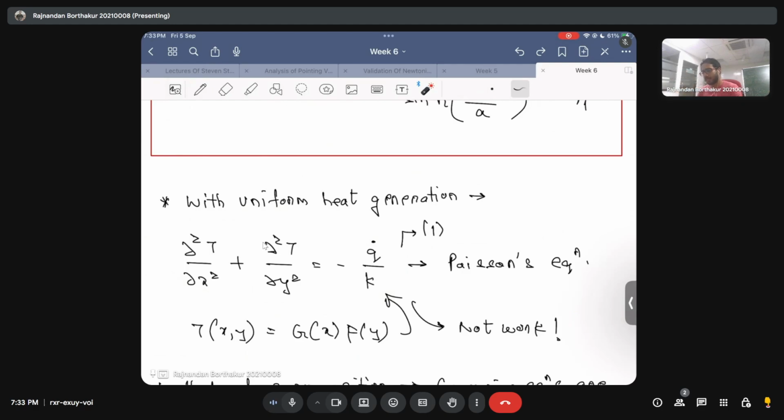I believe this is a little bit involved session in terms of the maths that we did, but I also hope that you tried to understand the nuances, and I tried to reflect the nuances of these techniques, specifically the method of separation of variables and how it works, what the Laplace equation is, what the Poisson equation is, why we are dealing with a 2D heat transfer case, what the orthogonality principle is, the series solution, eigenvalues, and things like that. And finally we ended by discussing the method of superposition, and in what cases it actually works.